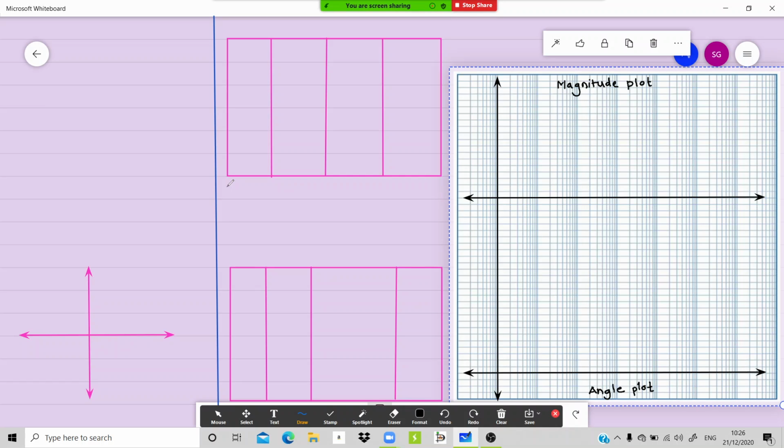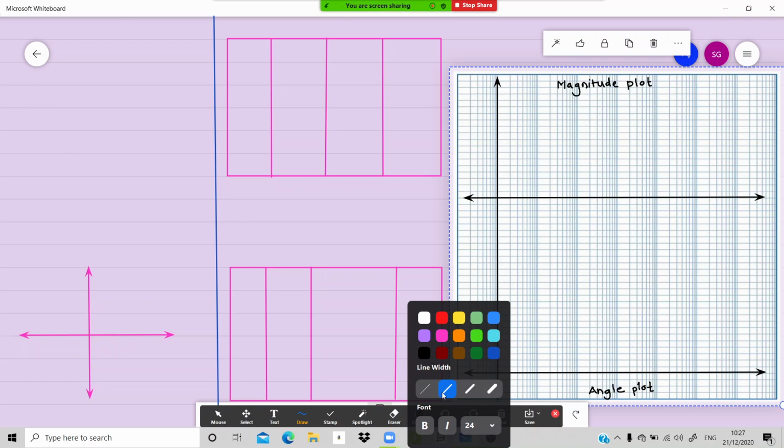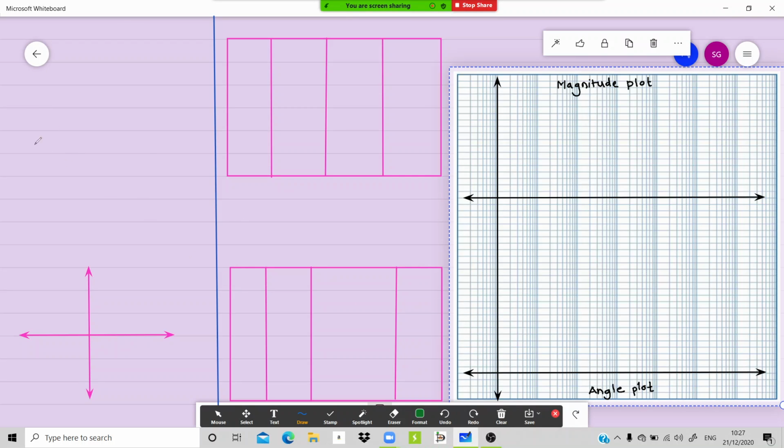Then we saw the repetition of the pole at the origin, that means 1 upon s squared is the transfer function of that particular system. In that case, the slope of the Bode plot line was minus 40 dB per decade. So A was the gain, B was the pole at origin, and now I am talking about C,